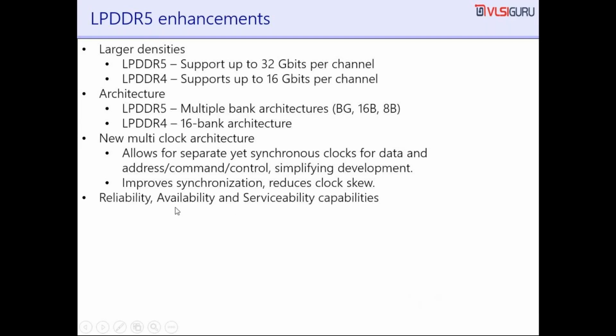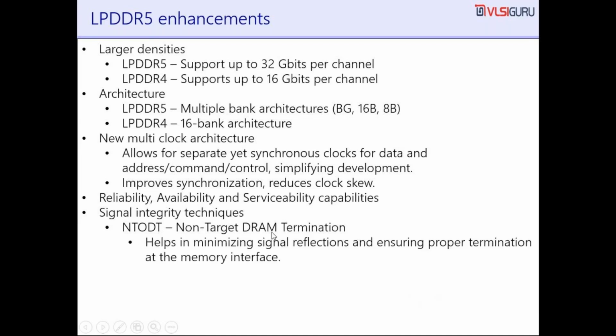It also has some features added for RAS, that is reliability, availability, and serviceability. And some signal integrity techniques have been introduced, like NT-ODT, non-target DRAM termination, which helps minimize signal reflections and ensure proper termination at the memory interface. It also has one tap DFE, decision feedback equalization, added.